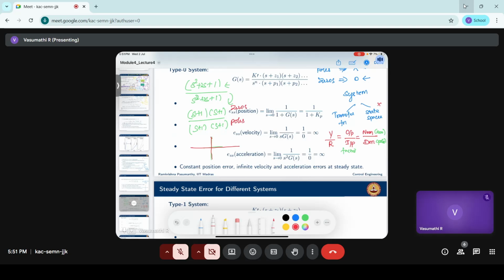So I will represent this, this is minus 1, let's take this plus 1. Then I will say two poles. Actually this is 2 times, and that cannot be distinguished. Two poles are at minus 1 and two zeros are at minus 1. That's how I can represent the pole zero representation of any system that looks like this.